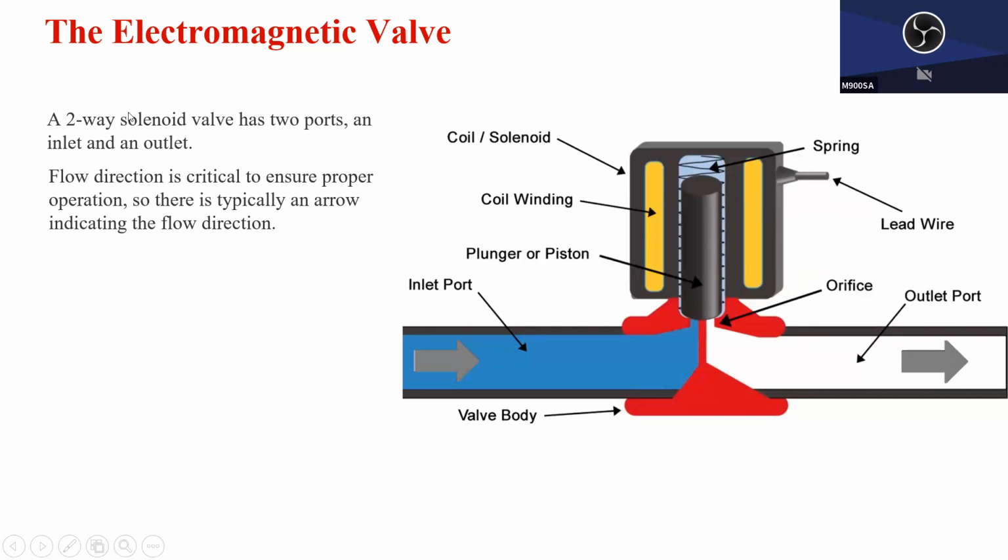And from this side, you can see the maximum unit of air or water this valve can handle. For example, for this one, it can handle 16 kilograms per square centimeter for air. And for water it is 13 kilograms per square centimeter. And the orifice of this solenoid is 3 millimeters. Yeah, that's it.